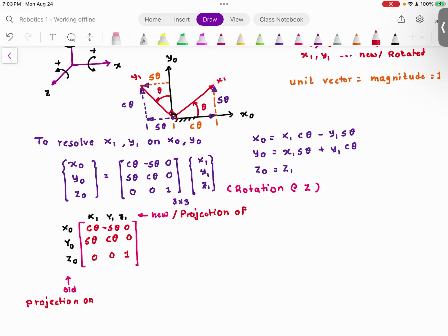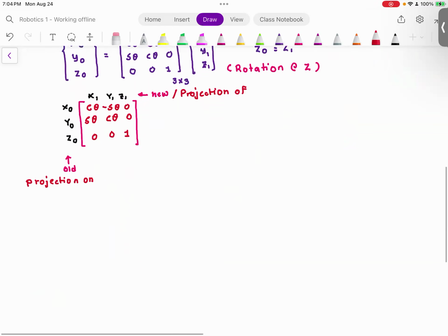Anyone studied robotics before coming here? Yeah. Then we talk about multiple rotation matrices. In Robotics 1, the only rotation matrix that we should be remembering is the rotation about z. I may ask you to derive the rotation matrices about x and y. But as far as forward kinematics is concerned, for all the robots, we should only be looking at the rotation about z. Everyone understood this? Any question? Okay, so we are ready to solve forward kinematics problems.